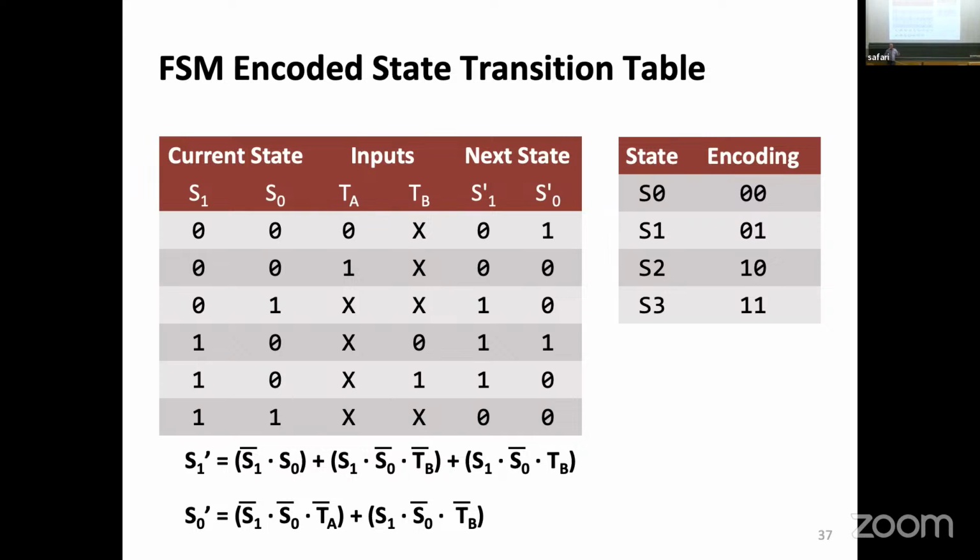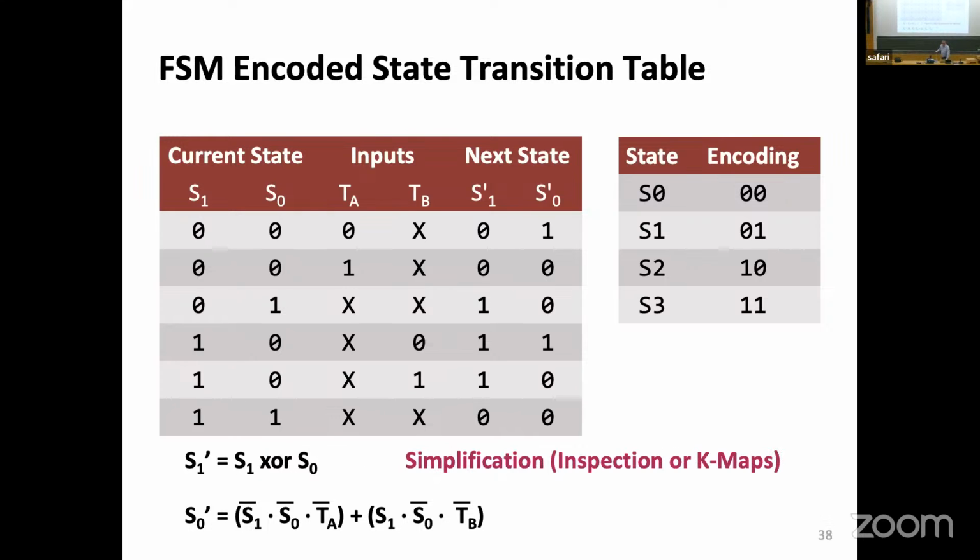Do you see how wonderful the exam questions could be? Write the next state equations. Okay, you look at S1, this one, and you can try to figure out what these things are. And using any method available to you, because it's a lot of things to type and write and draw circuits, we might even see some simplifications either through K-maps or by visual inspection. And we say, you know, this next state of S1 will be calculated like this. Good. I have a part of the circuit.